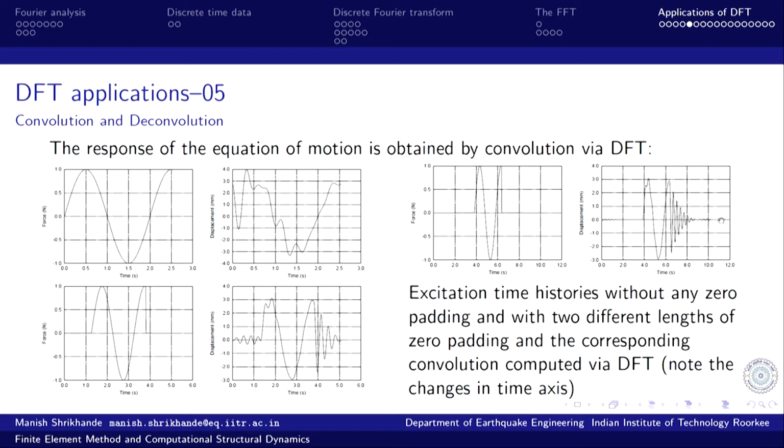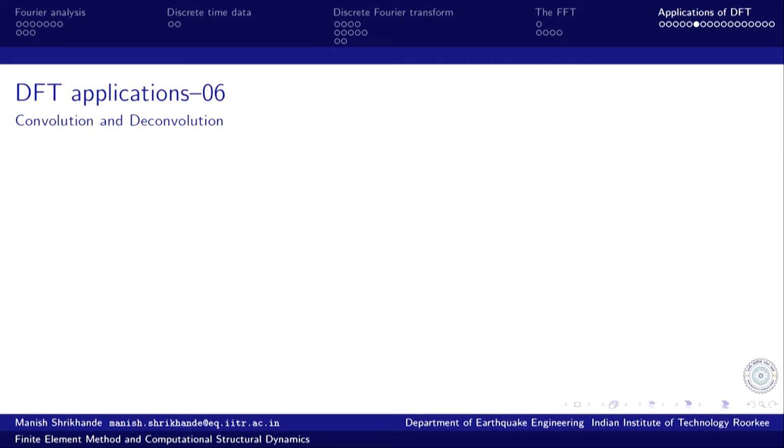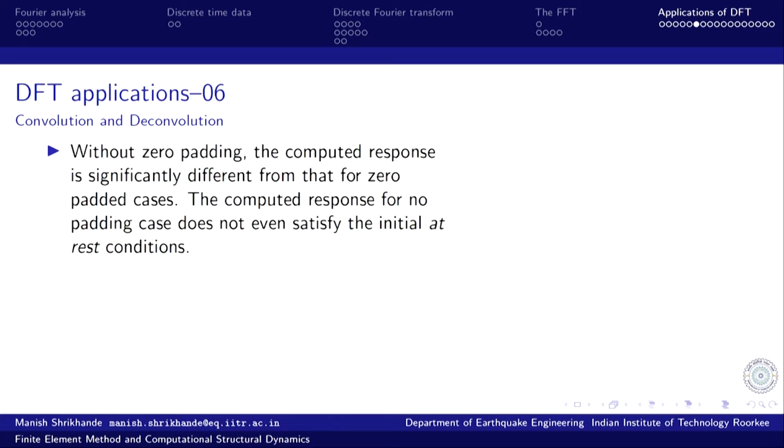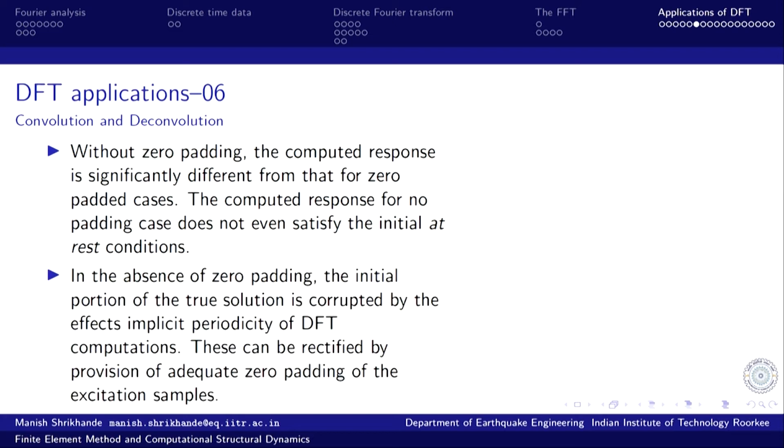So, if this free vibration response dies down considerably, then it has no effect whatsoever on the computed response, and the response computation would be more or less representative of the true response. So, without 0 padding, the computed response is significantly different from that for 0 padded cases. The computed response for the no padding case does not even satisfy the initial at rest conditions.